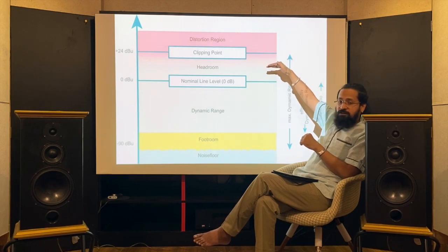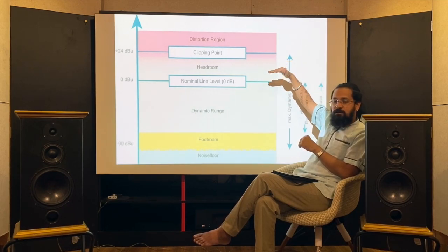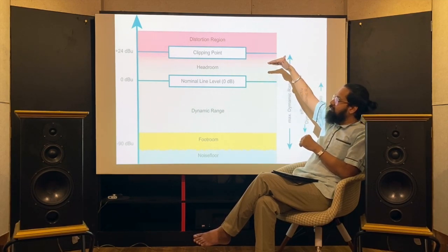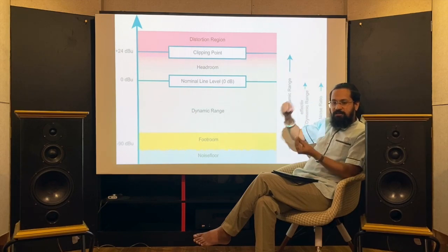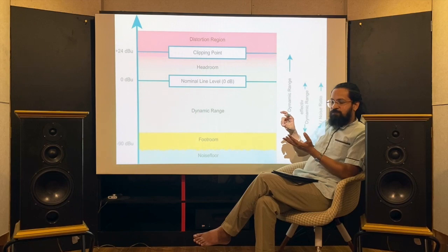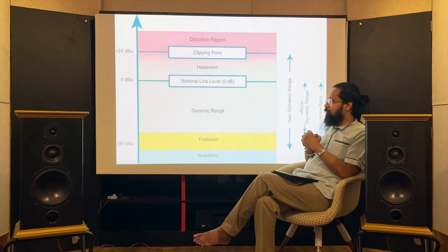If the recording engineer has not used the right kind of clipping eliminating DSP, or if he doesn't place the mics that are recording in the right direction, or doesn't set the gain in the microphones appropriately, you will have clipping at the recording source.